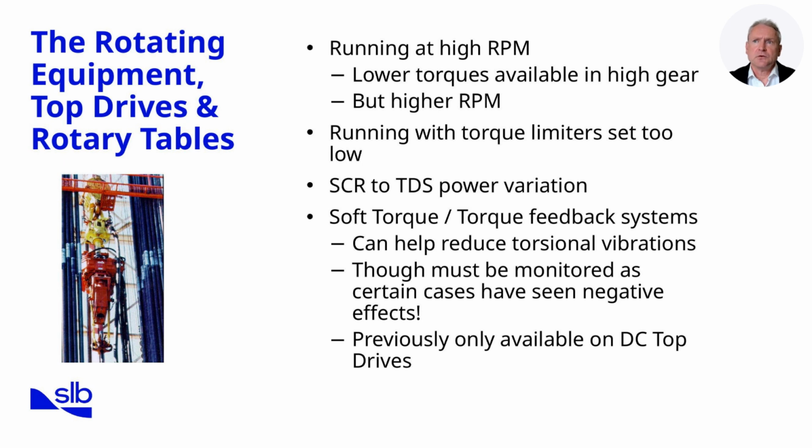Another factor is torque limiters. If they are set too conservatively, they restrict available torque and may cause premature stalls or unstable drilling response. Variability between different power systems also comes into play. For example, SCR-driven systems may produce different power characteristics compared to top drives.